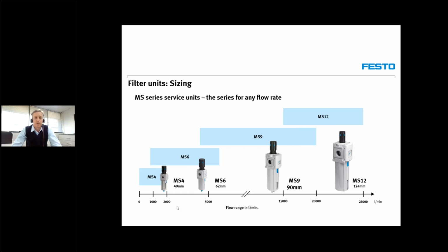So it is advisable not to go smaller in your supply line than the port on your actuator. But if you do get a stick slip effect, it is, as we mentioned, advisable to put a flow control on both sides of the cylinder so that you can generate a cushion at the back of your piston in order not to get a jerky movement.